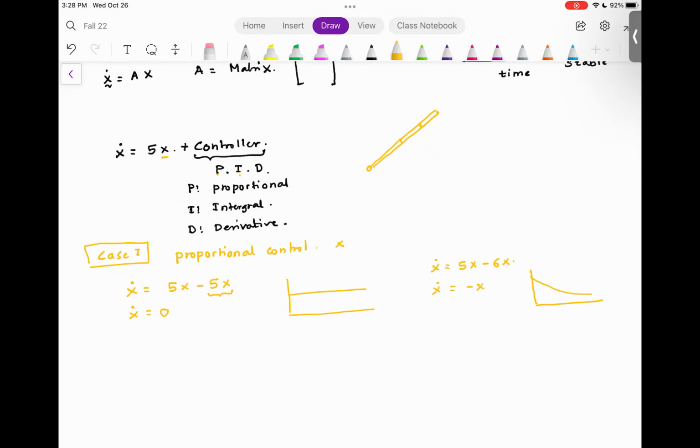Now, why do we need an integral and derivative term? So if my controller comprises of a term which is proportional to state, then it's a proportional control. If it includes the term that comprises of the derivative, for an example, plus or minus, say 0.1 x dot, that is derivative, and sometimes you can have maybe some type of an integral term, 0.01 integral x dt, and then this is called the integral term.